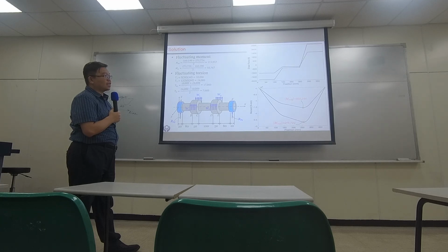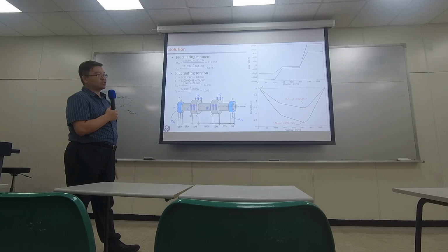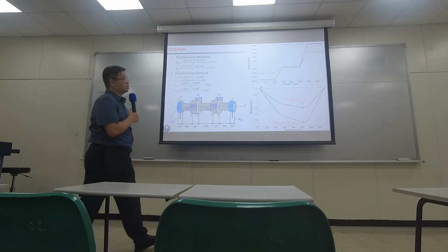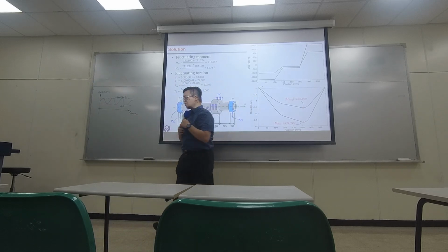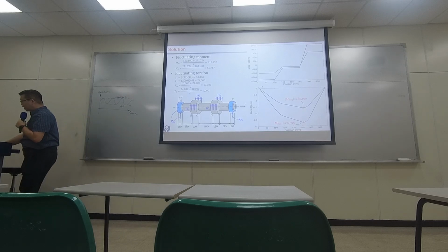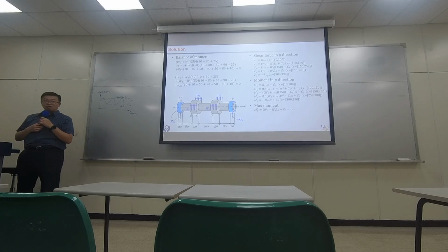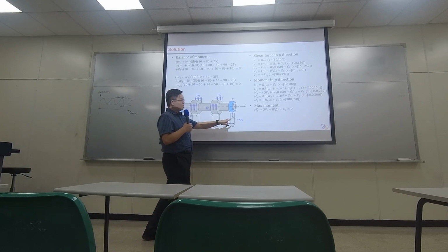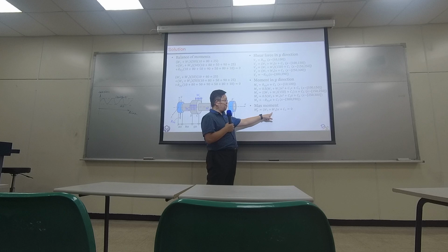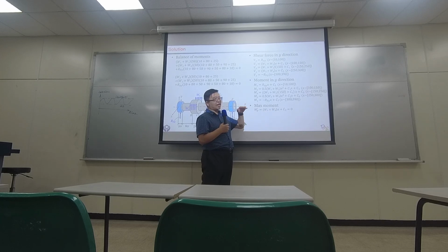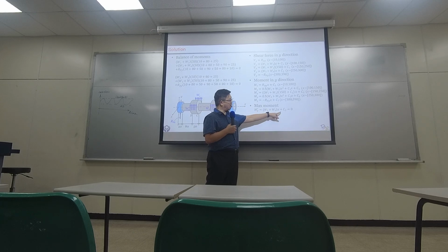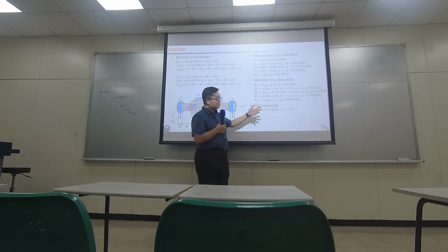So for mechanical design, we care about the worst loading position, the position with the largest stress. So I plug in the equation for finding the maximum moment. Of course, because the values of W3 and W4 are not the same in both conditions, the constants won't be the same.